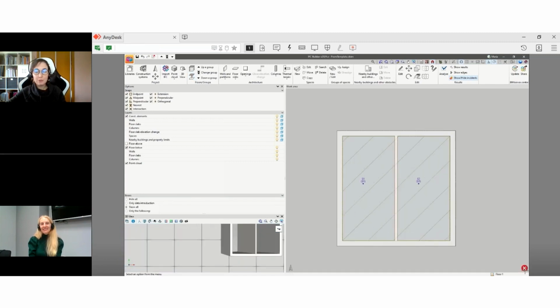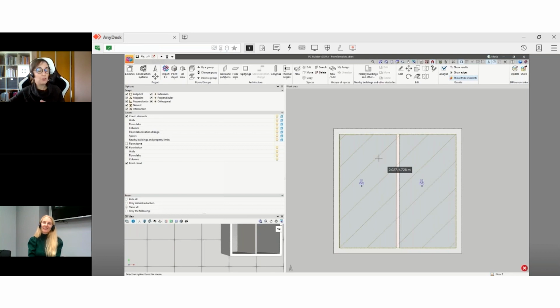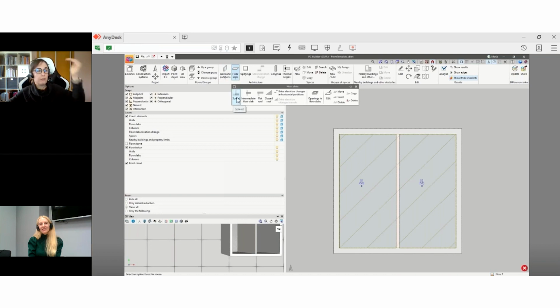And the change I want to make, okay, because look, now I see an error in ground floor. What happens here? A space cannot be defined beneath a raised floor slab or ground slab. Of course, I cannot have a screed and then another screed in the floor one, okay? This is the kind of thing I like showing, because then you see that this is an analysis tool. This is not only drawing. The program has this intelligence and is thinking, this doesn't make sense. One screed and then another screed.